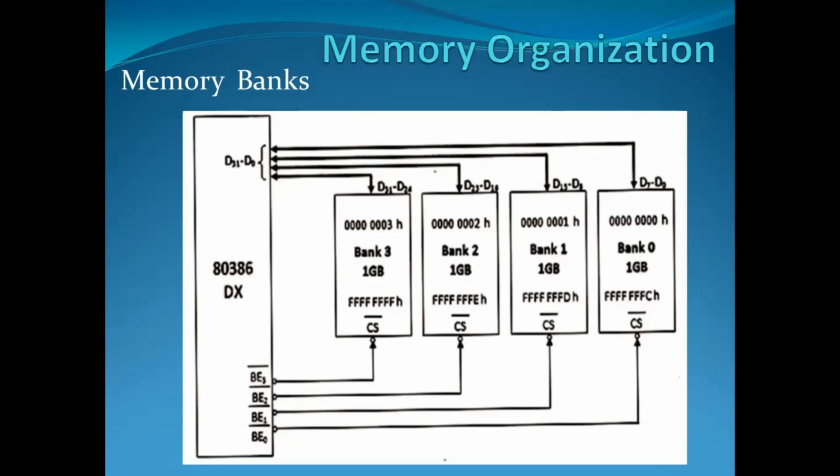The 386DX does not contain address connections A0 and A1 because they have been encoded as the bank enable signals. Likewise, a 386SX does not contain the A0 address pin because it is encoded in the BLE and BHE signals. The 80386EX addresses data in either two banks for 16-bit wide memory, or 8-bit memory, depending on whether BS8 is 1 or BS8 is equal to 0.